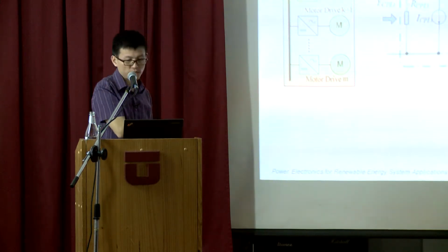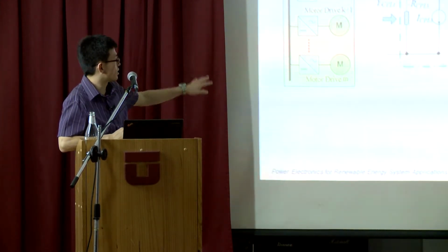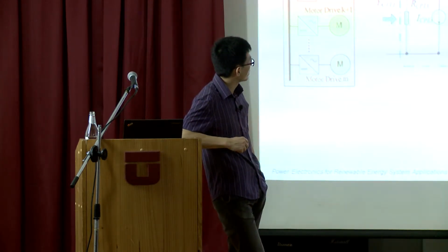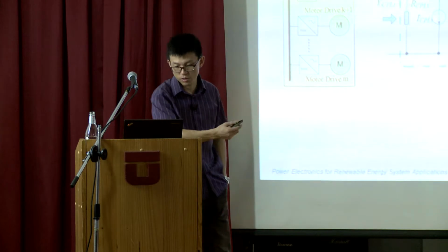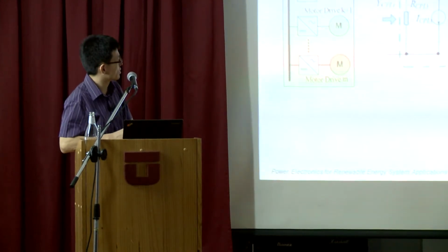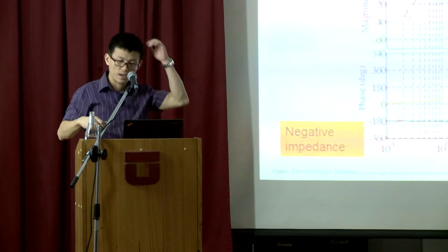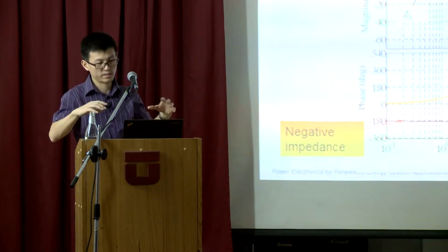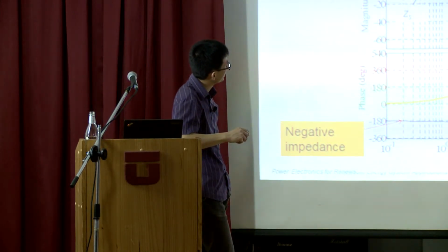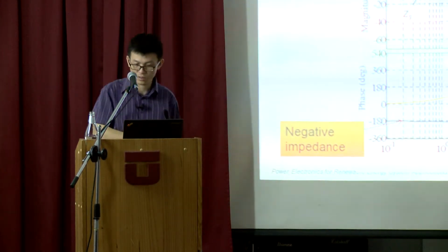Of course, when you do the analysis, you also have to look at the impedance for the loads. I'm not going into detail on this, but I mainly focus on the source side, because the load impedance, either constant power load or resistive load bank, is widely studied in other literature. What you find interesting, if you have multiple sources connected in parallel, is the load impedance ZL. I'll give you the Bode diagram of this load impedance as it is.